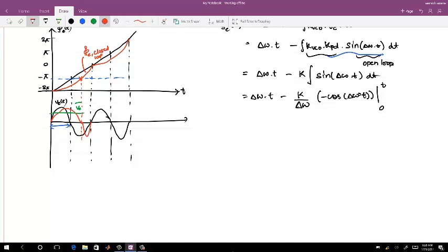So the thing is whether that voltage is large enough to correct for the frequency error or not. If that voltage is large enough, then you lock in. If it is not large enough, then you do not lock in this particular PLL.